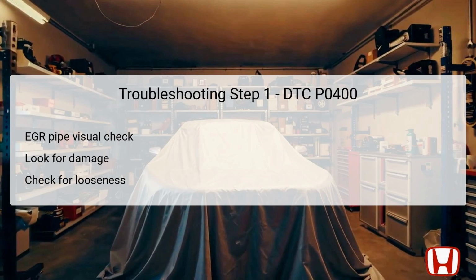If the EGR pipe shows signs of wear or damage, it needs to be either reconnected or replaced. This step serves to rule out the common issue of a compromised EGR pipe, which is often responsible for triggering this specific DTC. Should the pipe appear intact, you'll continue to the next diagnostic step.